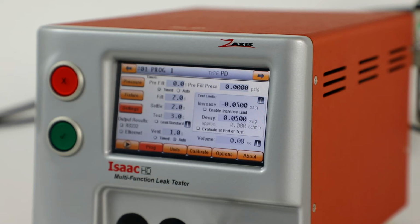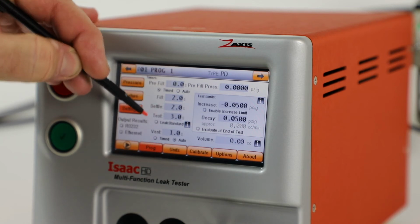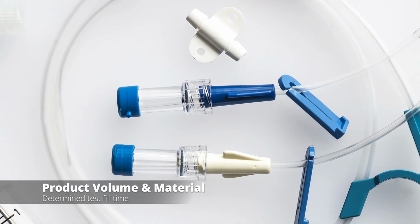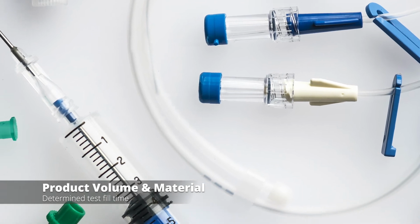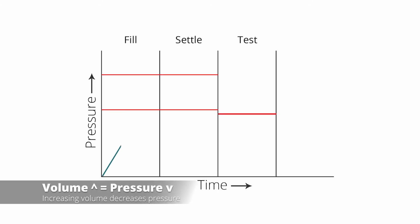These are our default values for a test setup. We have a 2-second fill, a 2-second settle, and a 3-second test. The volume of the part will determine how long we actually need to fill. The secondary item we need to think about during the fill is, do I have a soft part or a hard part? If the part is soft, it's going to act like a balloon. As we fill it with pressure and we don't have enough fill time, the part will continue to expand, and when we go into the settle and test step, that expansion will turn into a decay because the volume is increasing, and we will fail the test.